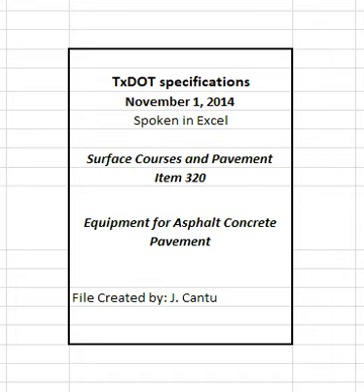2.1.1.4 Heating, drying, and mixing systems. Provide a dryer or mixing system to agitate the aggregate during heating. A heating system that controls the temperature during production to prevent aggregate and asphalt binder damage. A heating system that completely burns fuel and leaves no residue, and a recording thermometer that continuously measures and records the mixture discharge temperature. 2.1.1.5 Dust collection system. Provide a dust collection system to collect fines generated by the drying and mixing process and reintroduce them into the mixing drum.